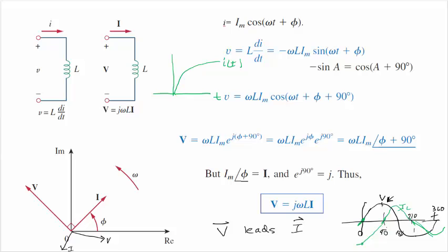So as the circuit time progresses and 5 L/R time constants go by, the current will be at a maximum through the inductor in the steady state. And then similarly, the voltage in the inductor does an exponential decay. So when I is a maximum, V is a minimum. And you can see that in the sinusoidal behavior of the circuit. So that's trying to make physical sense of what's happening.